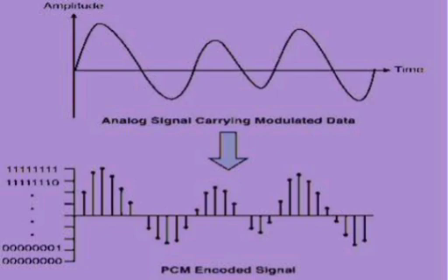Rx of 0 gives the power content of a power signal. Rx of 0 gives the energy content of an energy signal. The Fourier transform of Rx of tau gives the power spectral density for a power signal, and the energy spectral density for an energy signal.